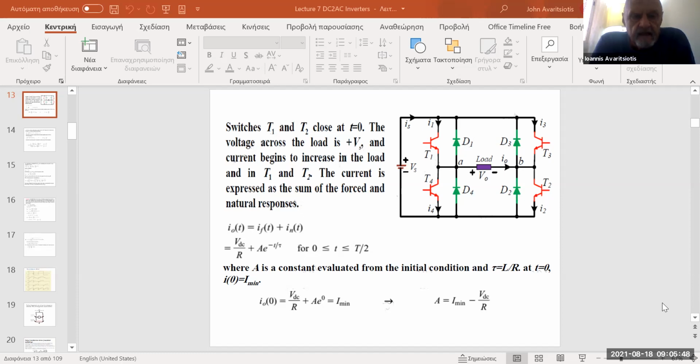If we assume that during a period of time, during a time slot, if you remember, we discussed yesterday the waveforms, the voltage waveform across the load when the load was resistive, of course, just to use a simple resistive load. We had a square waveform across the load, if you remember. And assuming that the load is resistive, then in this case,